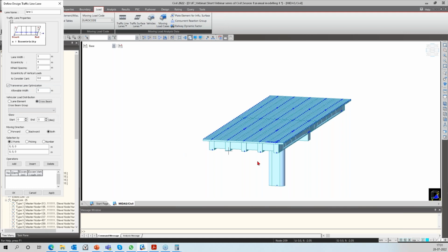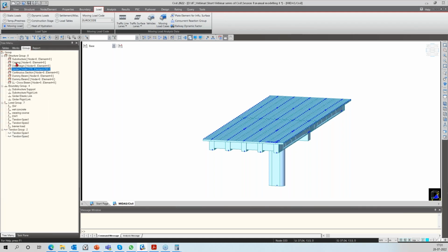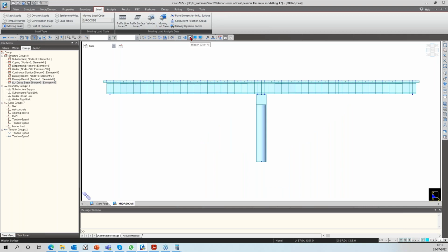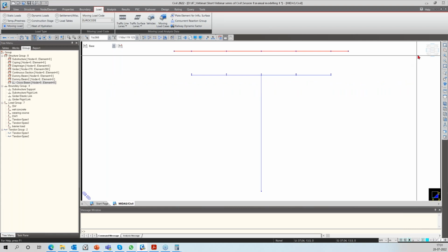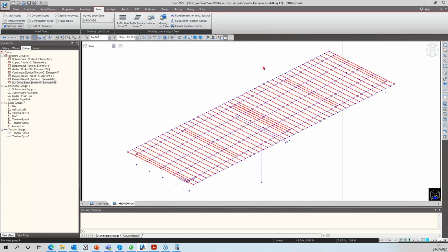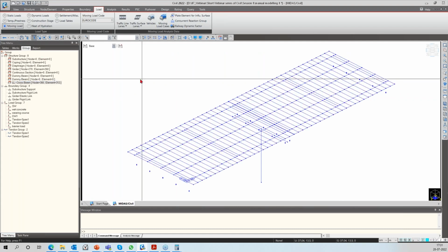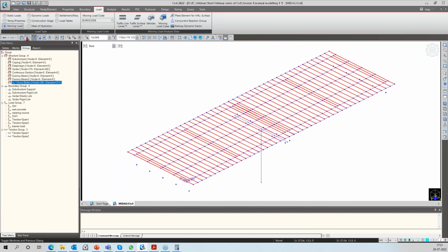Cross beams, now you need cross beams, that is our transverse elements. So let's create some members in those cross beams. So live load cross beams are nothing but our transverse members. So for that, let us do the selection of only the elements spanning in the y direction. So let's hide and select in this way and use drag and drop feature to apply this particular structure group.